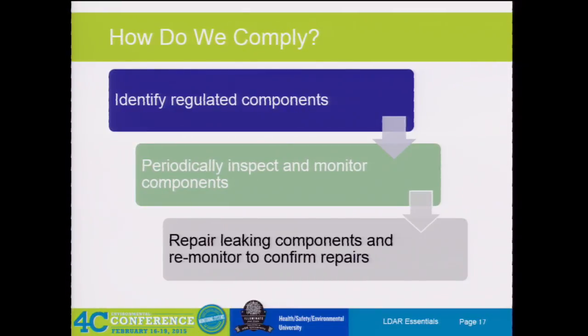So you want to make sure that if you ever do DTM audits, you have certain folks walk them down out in the field, because they might have put in a new platform. They might have added a support structure or something so that these components are now not DTM. You don't want to get hit hard if somebody comes in and looks at your program. You want to keep it evergreen. And for DTMs, most folks have a 3% cap depending on the rule. So you can pick a unit a month or a section a month when your guys have a little extra time at the end. It's a very good little QA/QC method to do.